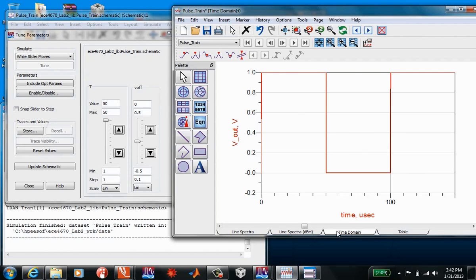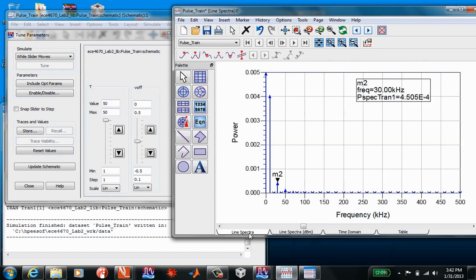So when you have it looking like a square wave, you're going to get the DC. I'm going to get a spike at the fundamental, and at the second harmonic, that one is nulled out. Remember, we were talking last time about odd half-wave symmetry? This is an example of a waveform that has odd half-wave symmetry.